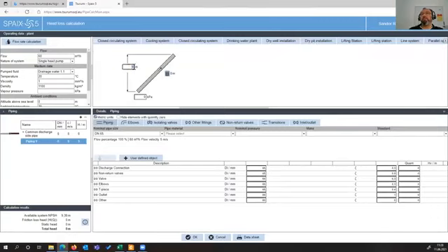So once again, we need to add 30 meters. And at this stage, the system already selected a nominal diameter for the pipes, DN 65. So what could be the reason to refuse to use this nominal diameter? It's quite easy. It's the high flow velocity.